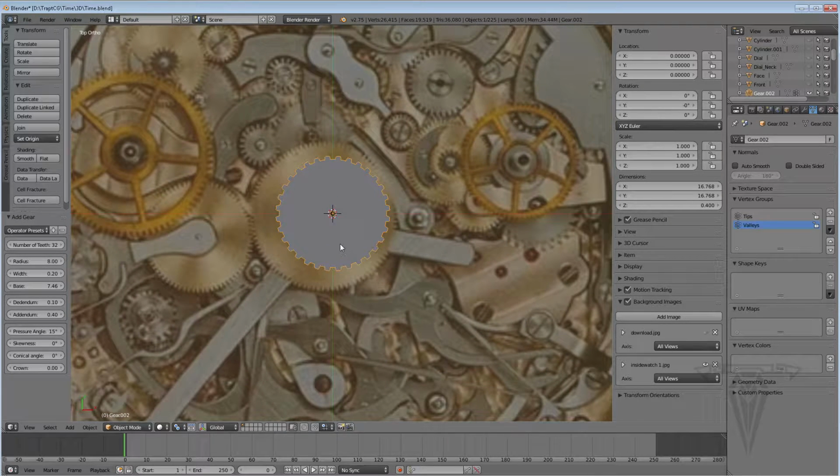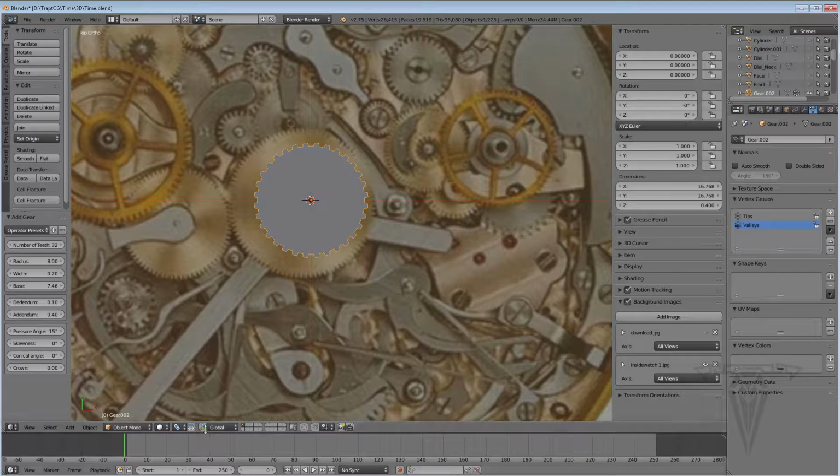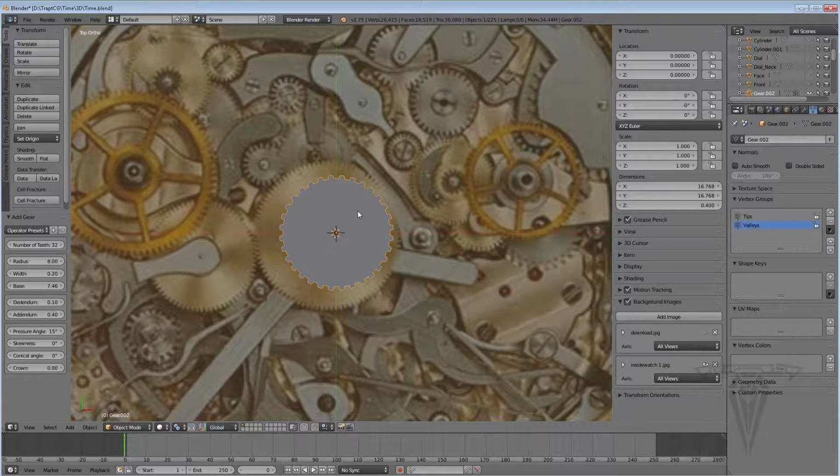So I'm going to go ahead and move this off to the side. I'm going to reactivate my move tool. Now, selection mode, which is this, allows me to just select things. If I wanted to move it and not have to come down to the move tool, all I have to do is hit G on the keyboard. I haven't really talked about G or rotate, but R is rotate, G is move, which is called grab actually.